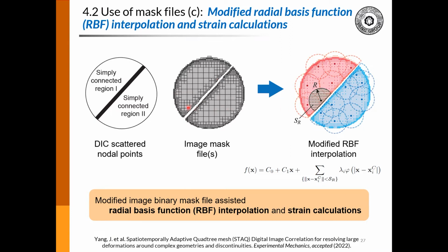Basically, I have so many control points here, and I want to compute the gradients of the displacement. That's the strain fields. So I always choose the data points that are simply connected and on the same side of the crack.